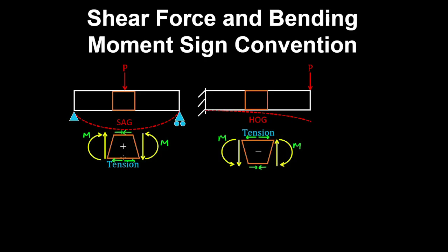And for example, if you had a concrete beam, cracks develop in tension, so you'd put your reinforcement in the bottom of that beam to prevent that crack from propagating. And given concrete's weak in tension, when you have hogging moments, the crack will develop from the top, so you'd put your reinforcement in the top of the beam to prevent that crack from propagating.